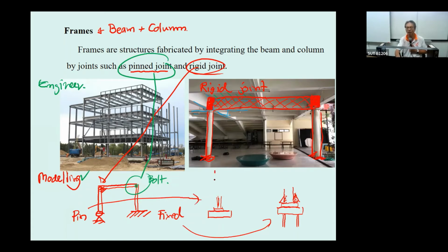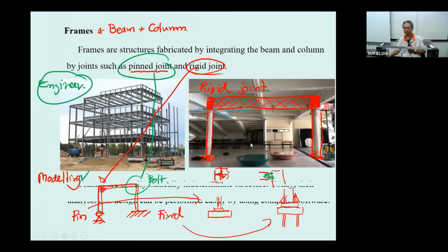And for the connection also, if you like to connect it as the fix, you have to weld it properly. If you like to make it as the pin, you may use the bolt to bolt this one together. They have a lot of detail in this. As an engineer, you are required to know this kind of thing.